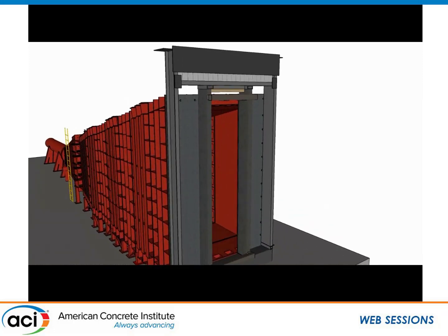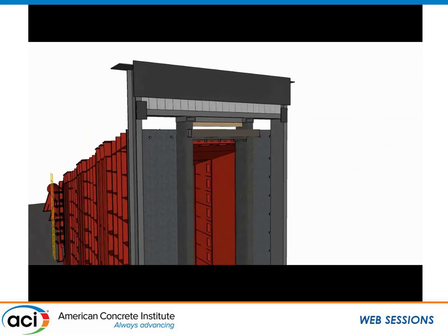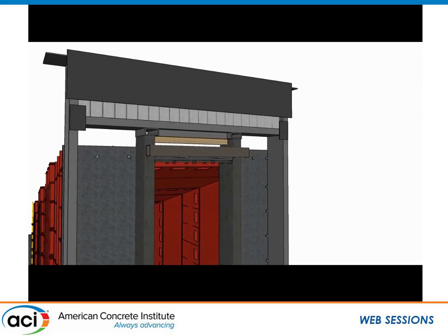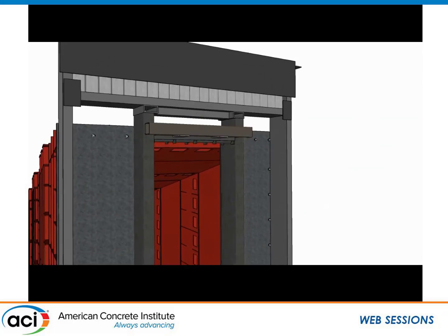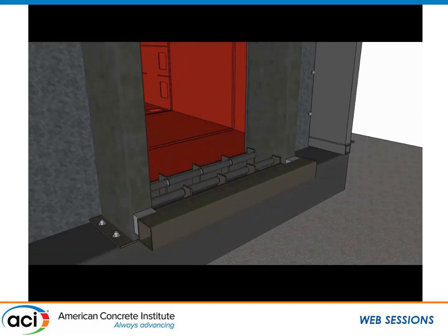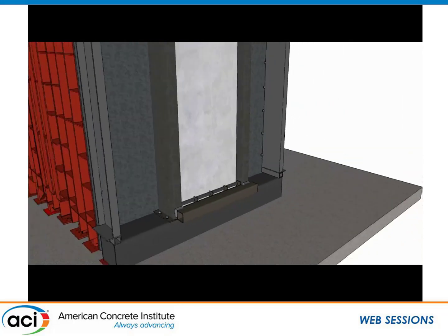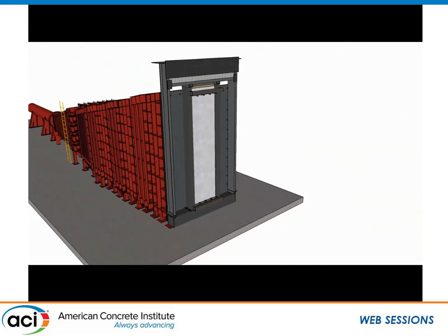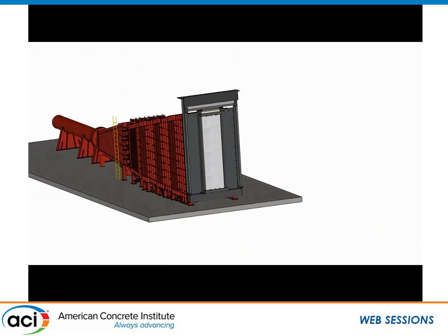At the top right now, what we're looking at is a load bearing apparatus. This is something that we designed. It's kind of the first of its nature. The way that it works is a series of airbags, and we pressurize those prior to the test, apply an axial load on top of the wall. So that's the wall there in place now. And then that axial load is essentially maintained throughout the entire test.